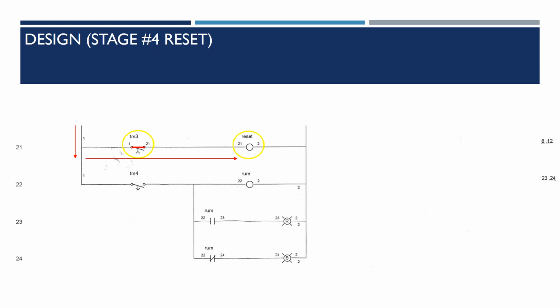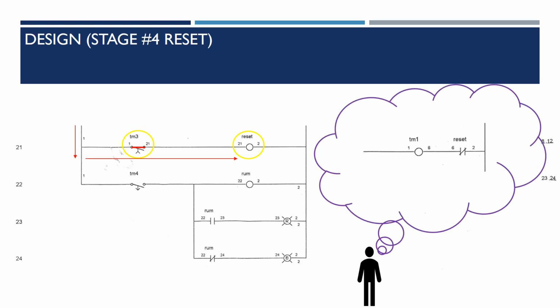And we talked about it a little bit above, if you can remember back that far. We have a normally closed reset contact attached to all of our relay coils that were energized. At this point, when that reset coil energizes, it will open up each of the contacts, and that will open the circuit, essentially de-energizing the coil and putting all of our contacts back to its normal state.